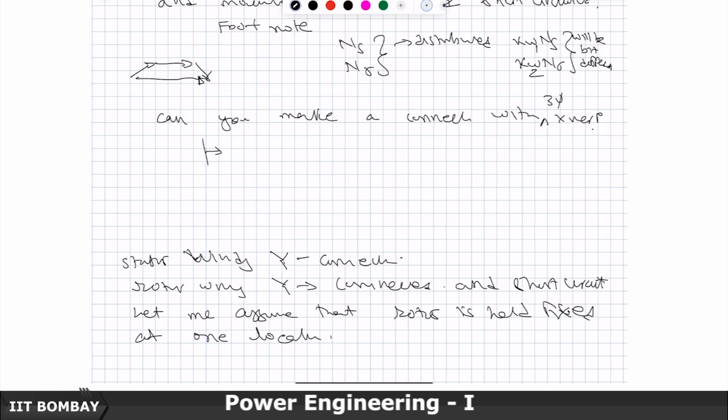See, the 3-phase windings of the power transformer that we discussed earlier in the course are also distributed, are they not? Nobody is concentrating them. You have 3 limbs in a core type of transformer and then you wind one like this, so it is in space, then the other one is also in space. But the geometry is not a circular geometry.